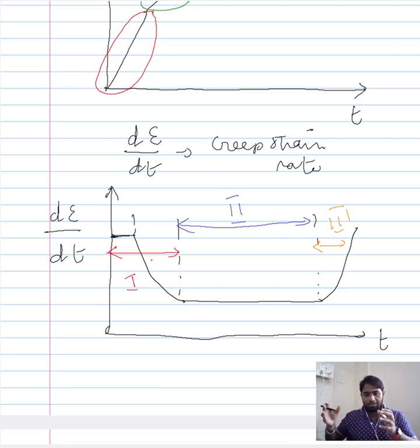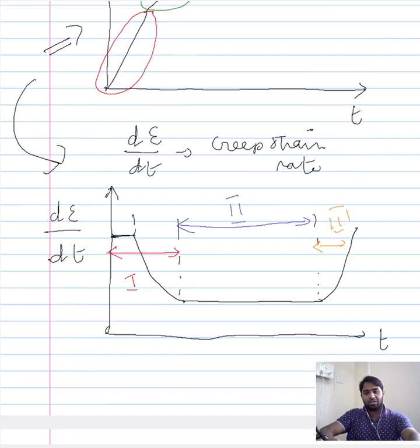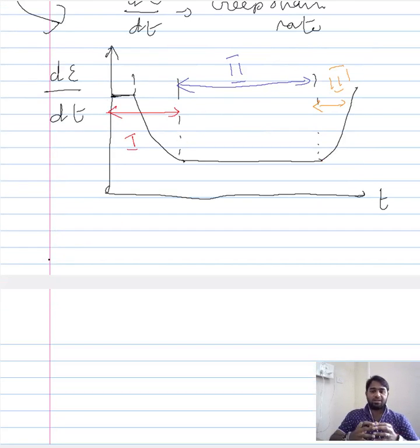the creep testing. We were able to section it, and the nature of the change in the creep rate over the period of time, how the creep rate changes over time, we were able to illustrate by just considering the creep curve. Based on this creep curve here, we were able to illustrate how the creep rate or the strain rate changes during the duration of the overall creep.